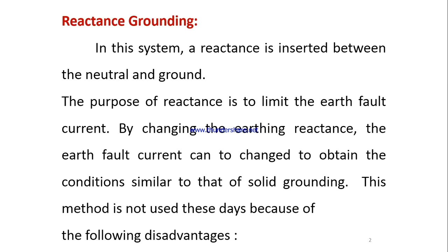The main purpose of the reactance grounding is to replace the resistance so that the power will not be dissipated too much. It can be stored and then discharged, etc. This is the reason for using this reactance grounding. And then by changing the value, earth fault current can also be changed to obtain a condition similar to that